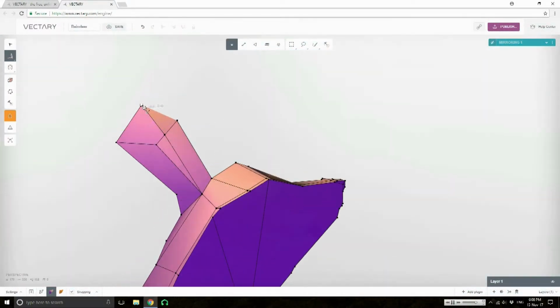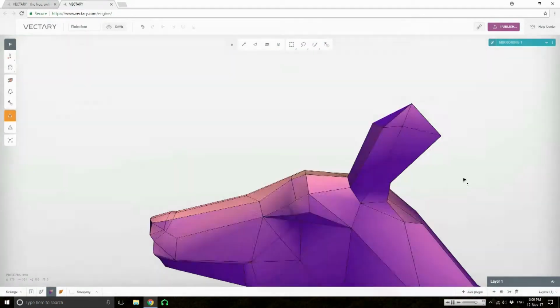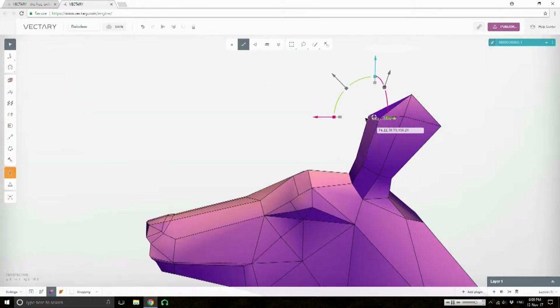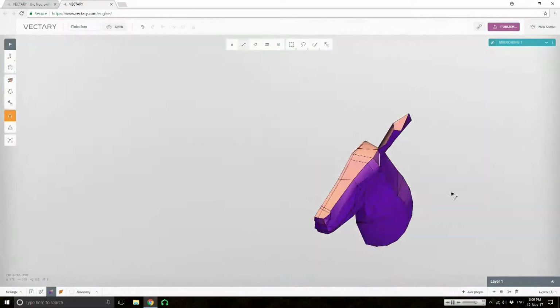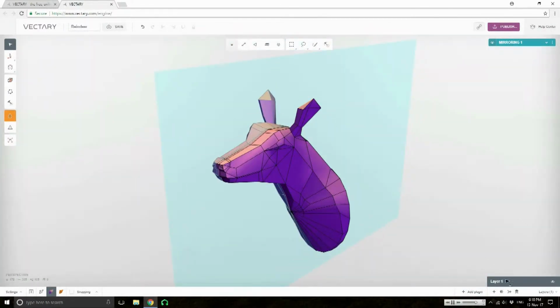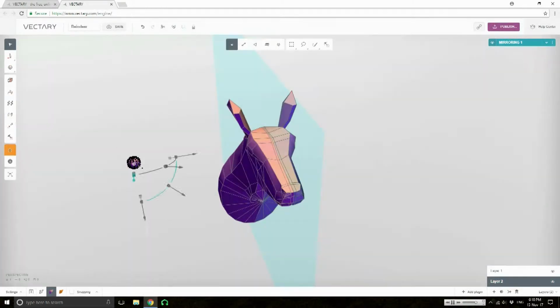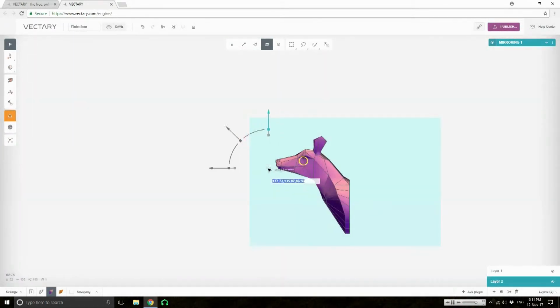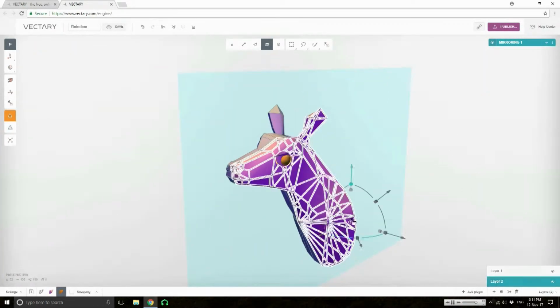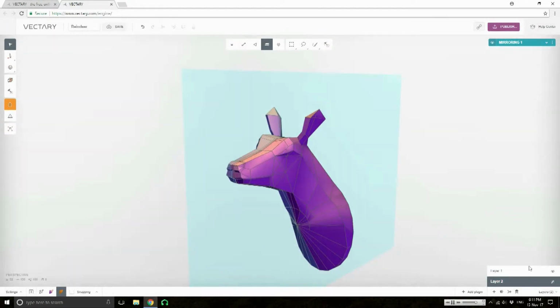You can delete surfaces and then use one of the tools to instantly fill the surface, and that's quite useful, particularly later on when you come across little bits of surface which don't properly knit together, and they create sort of weird little drag marks or pulls in the surface.